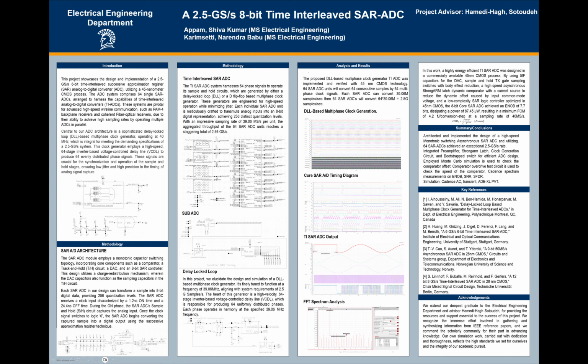We had a proper output signal after the DAC. So this is the total time interleaved SAR ADC structure that we implemented in 45 nanometer CMOS technology, Cadence GPDK.